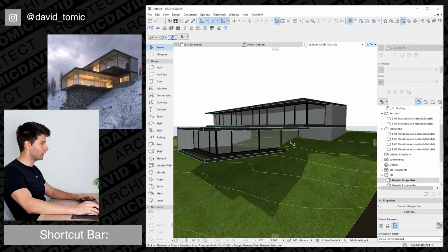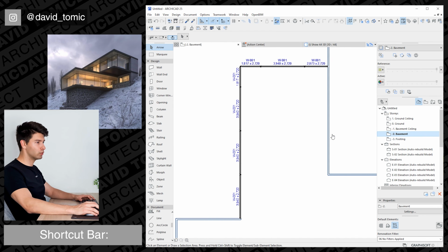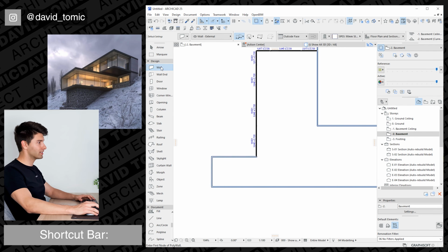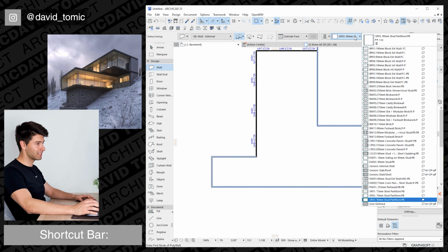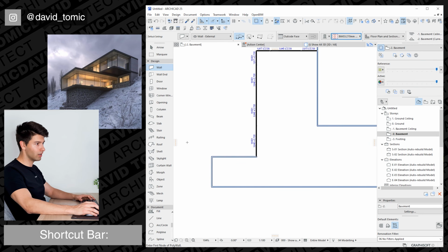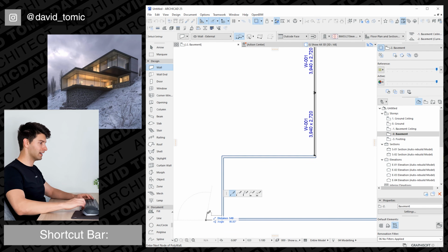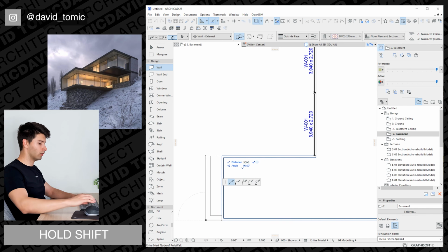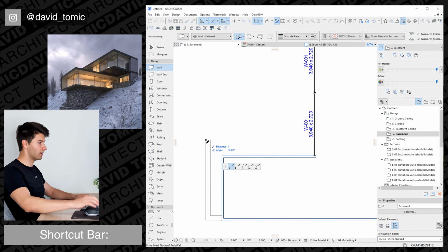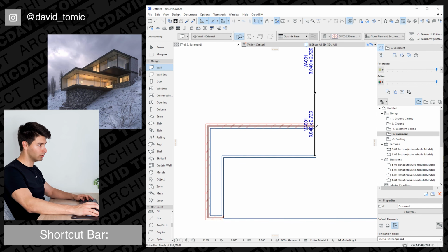What you will notice is now that we need a retaining wall cutting right into that panel of glass and wrapping back around this house to create some sort of planter. So we're going to come into our basement floor plan. I'm going to select my wall tool and select a nice big chunky brick wall. So let's go block work of 270 millimeters. Then I'm going to start at the edge here, go 1 meter out, hold the Shift key, go 1 meter past that. So 5 meters, maybe let's go 6 meters actually, and then return back into our window over here.